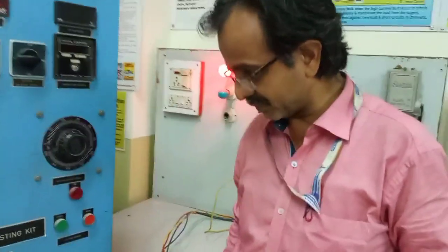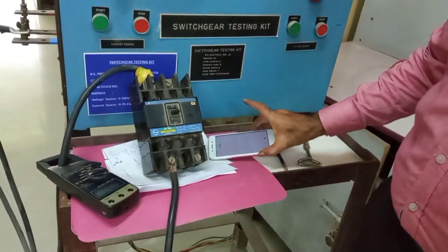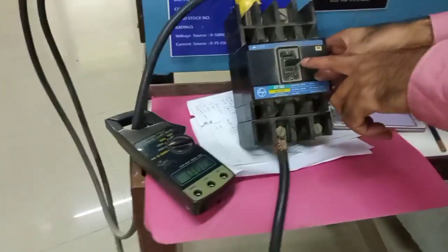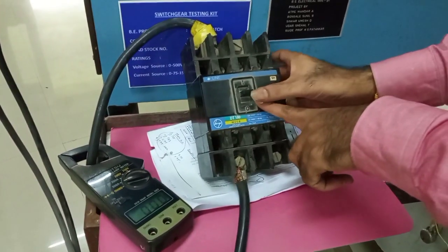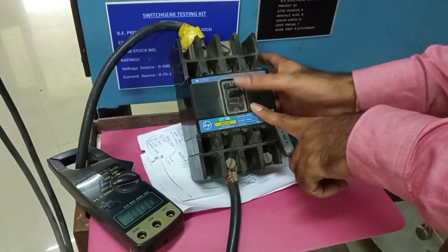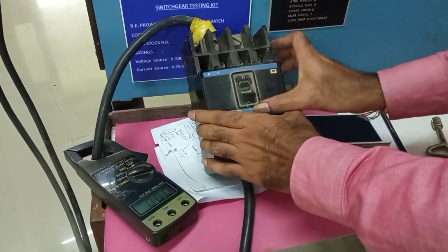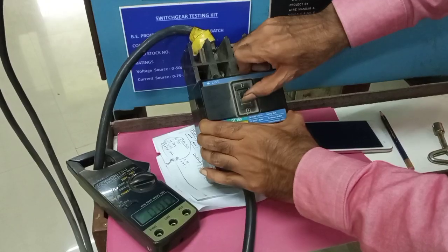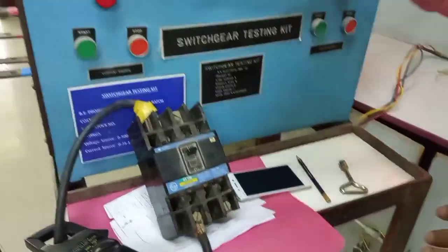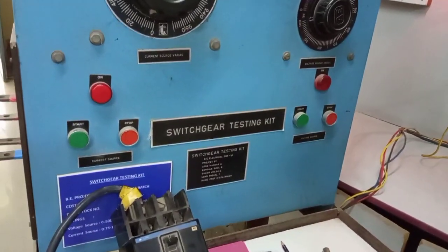Okay, second reading. So for this we have to pass 200 ampere current, and at the same time we have to start the timer. But before that, you can see for the first reading, when MCCB trips, it has taken the middle position. From this middle position, if you go to on, it is not going because interlocking is there. So from middle position we have to compulsorily come to off position, and now from this off I will go to on directly. So now MCCB is made in on position, and for this now we have to pass 200 ampere current. So I will switch on the supply.